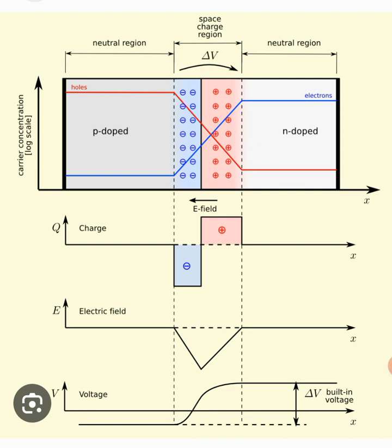Now, when two semiconductor materials are joined to each other, it is called a PN junction. If we want electricity to flow in this device or in this junction, we apply an external voltage to this PN junction, and by means of the externally applied electric field, we have to overcome the depletion region voltage, that is the barrier voltage or built-in voltage, so that the electrons will flow from one region to another region.